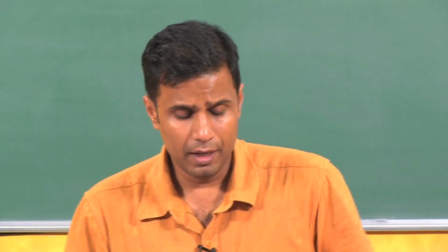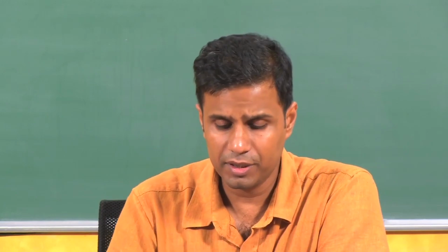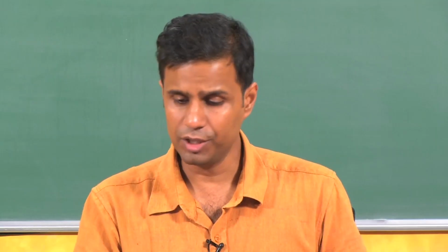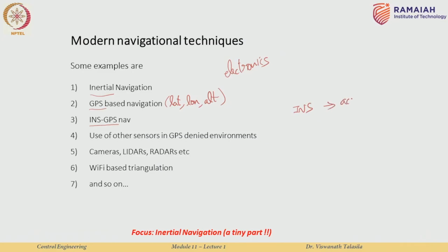The other thing is inertial navigation, we will be discussing that a lot in these lectures, and inertial navigation uses accelerometers and gyroscopes. The really accurate type of navigation on earth is by a combination of INS and GPS. So, it is basically a fusion, it is called INS GPS system, inertial nav GPS based system. And here again, as we have talked about in the dead reckoning and celestial navigation, the inertial navigation system is very accurate over small time scales, and GPS has bounded error.